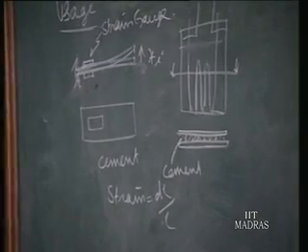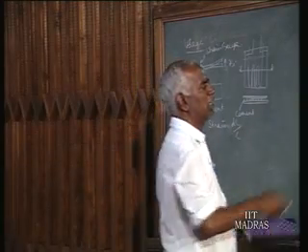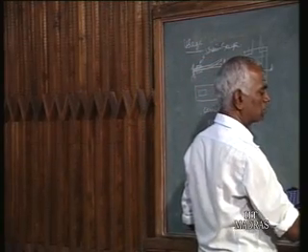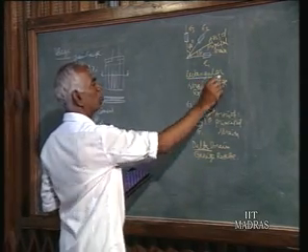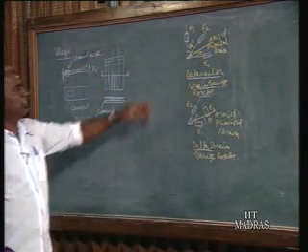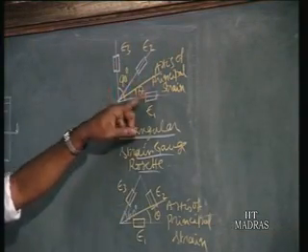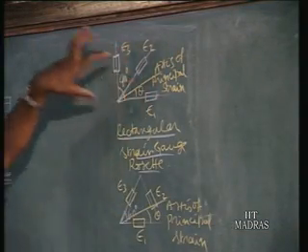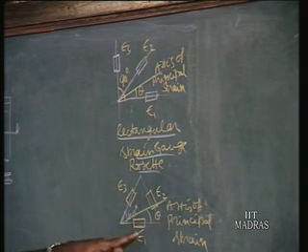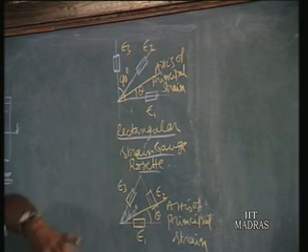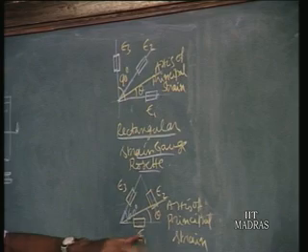In such instances, we go for strain gauge rosettes. We have two types of rosettes: delta strain gauge rosettes and rectangular strain gauge rosettes. That is, three strain gauges are fixed. In the case of rectangular rosettes, it is 90 degrees and the middle is 45 degrees, fixed on the structure. Similarly, you can go for delta. These three strain gauges, epsilon 1, epsilon 2, epsilon 3, are fixed at 60 degrees to each other, and you measure each strain with a separate circuit.